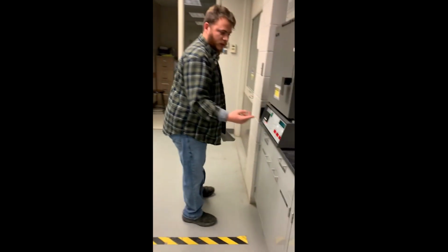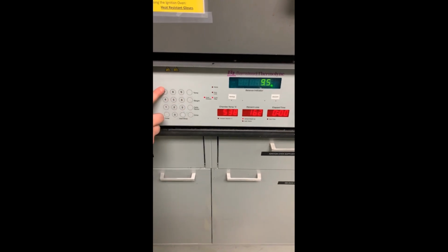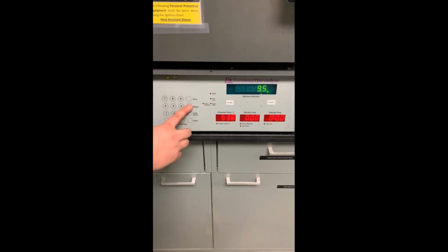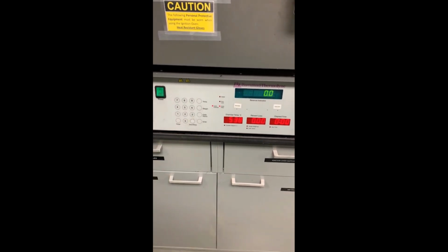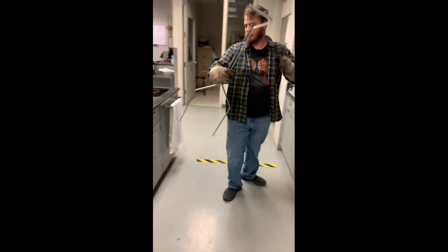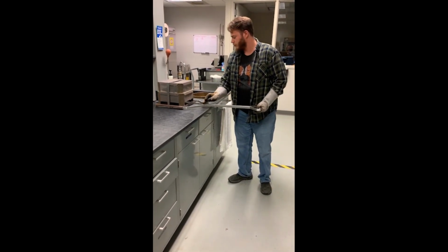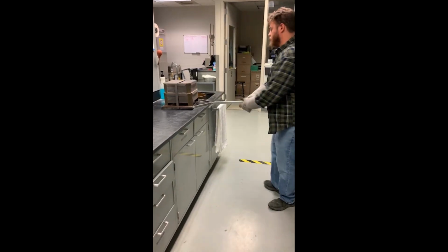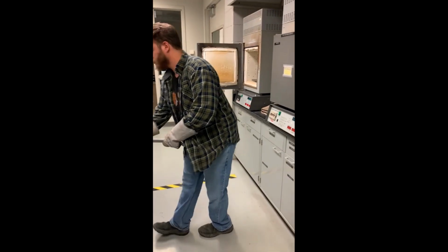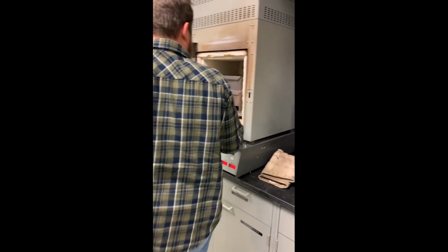Bring the sample to the ignition oven and enter your sample weight. Re-hit the weight button to make sure you have the correct weight of sample, and then zero the scale on the oven. Always make sure to wear proper protective equipment. Place the sample in the oven by putting it all the way to the back and then down onto it, not sliding across the bottom plate.